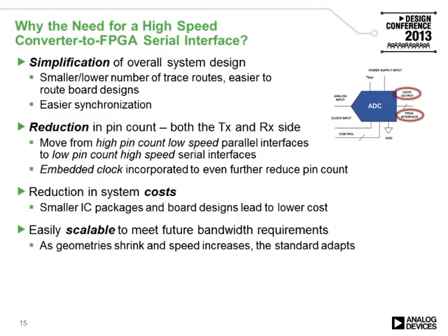There are 2 obvious ways to add bandwidth. Either increase the bus speed or add parallel channels. Prior to the advent of high-speed interfaces, the latter approach was often chosen, resulting in wide buses with all their implications when it comes to system design. To simplify system design and further scale bandwidth requirements, a new approach is taken by using high-speed serial interfaces.